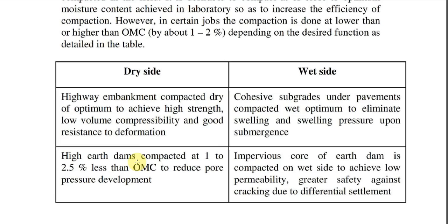There is less pore pressure on the dry side of optimum because the voids are not completely filled with water. Hence, the pore pressure will be less. Whereas on the wet side of the optimum, pores are completely filled with water. That's why pore pressure will be more.